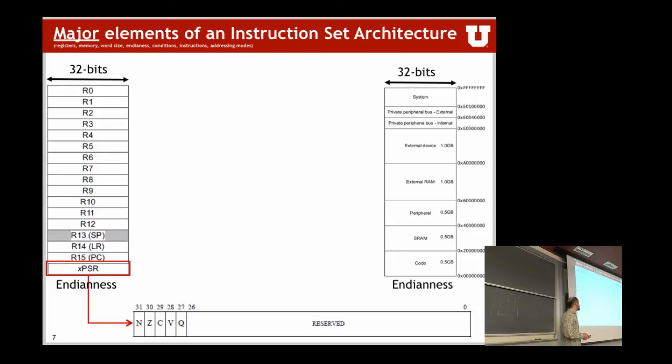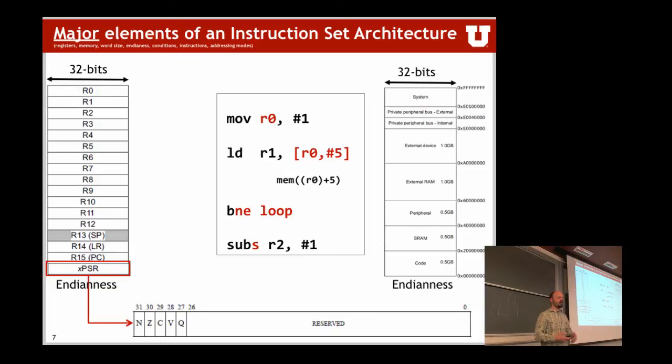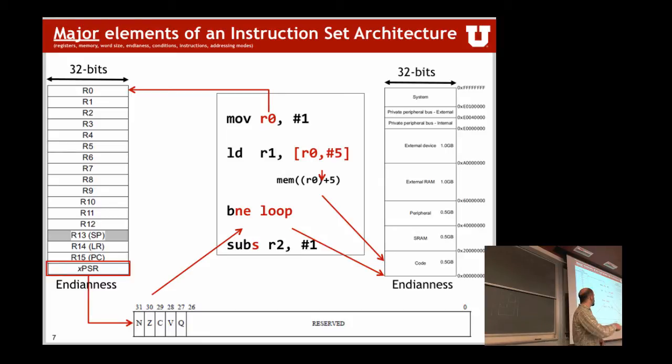We had the status register that has a couple of different specific values and conditionals that we can execute code from. And of course, we have assembly code that does operations on the registers to store and get data, or to get information from the memory, from code execution that is conditional on the different status registers, and links or labels that point into memory themselves to jump to or get data from.